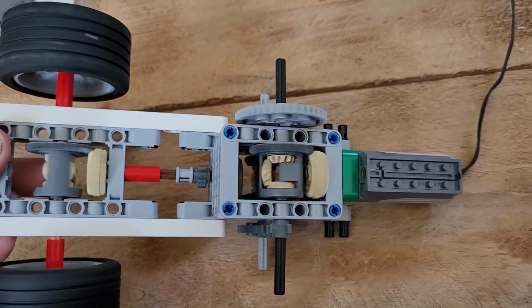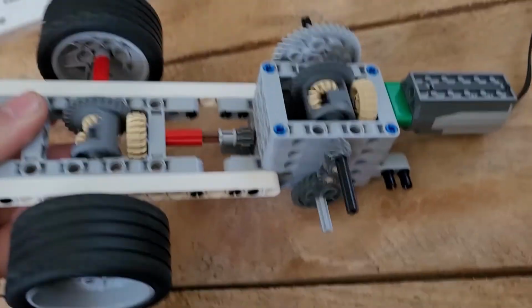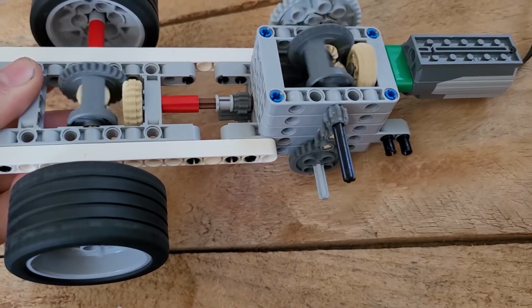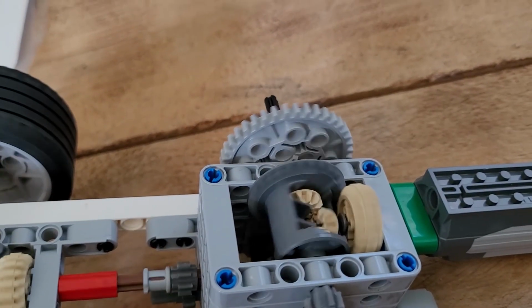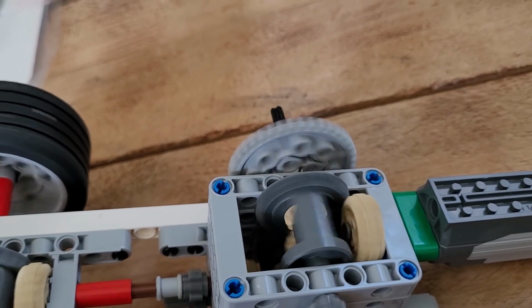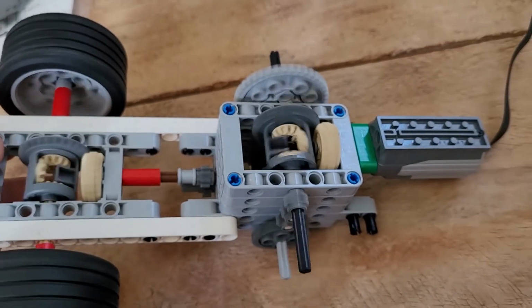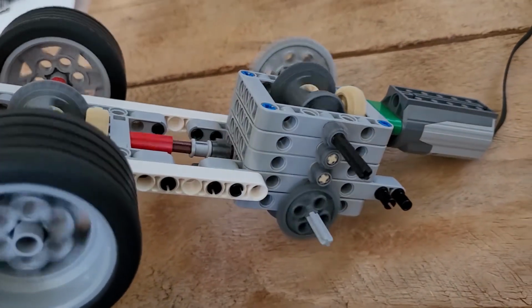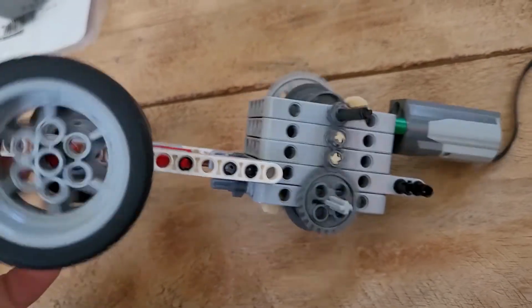Now as we put a little bit of resistance on here, you can see that we're now slowing that larger gear and spinning more on this lower side. And now watch that larger gear here. When I release the resistance, it spins back up again. So now we're in second. Now resistance, we're down into first. And the more resistance I put on it, the more it biases the more torque heavy side. So the side that's producing the most torque.